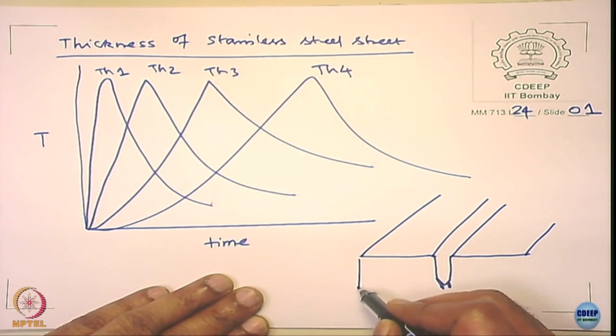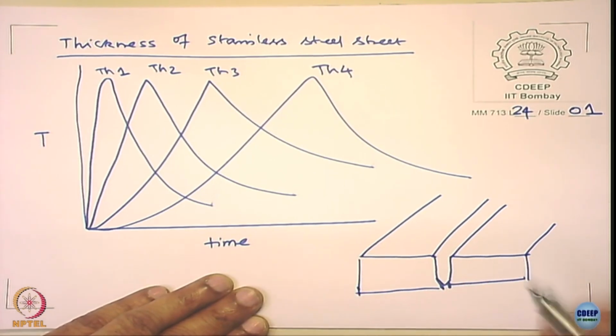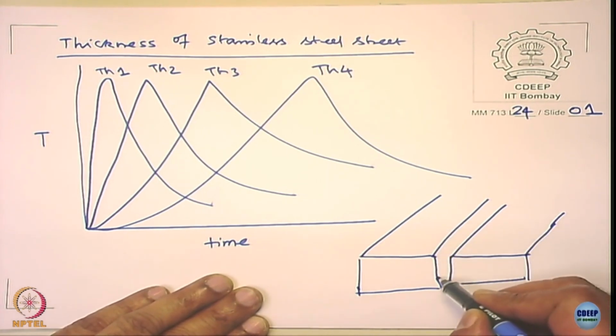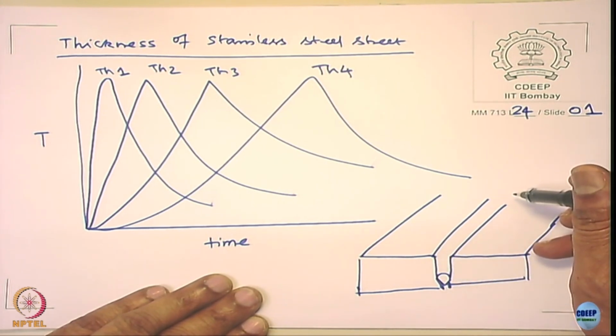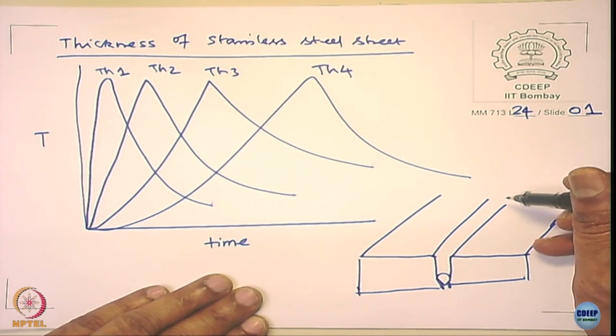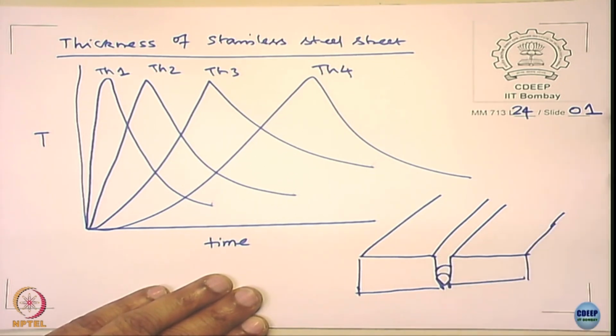Yes, it's a good answer, right. So you do not deposit at one go. You deposit once, you continue the layer, allow it to cool, then you deposit the second layer, and allow it to cool.